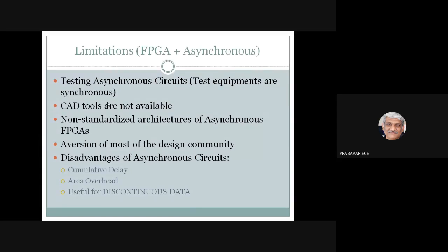And the cumulative delay, this is what I said. The output will be given to the next stage only if the next stage is free. Then it will give the acknowledgement only if the next stage is free. So every time the data delay gets accumulated. So a cumulative delay is experienced in the case of an asynchronous circuit. That is actually one disadvantage.